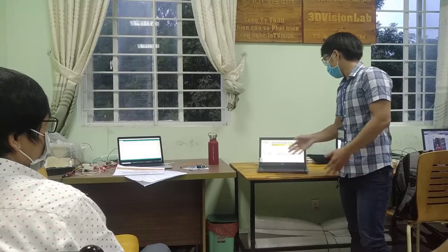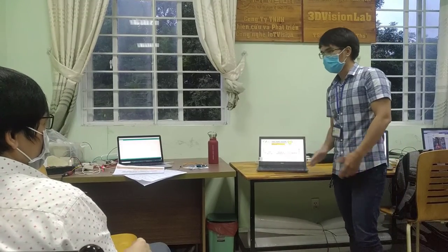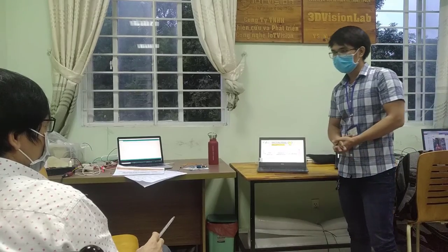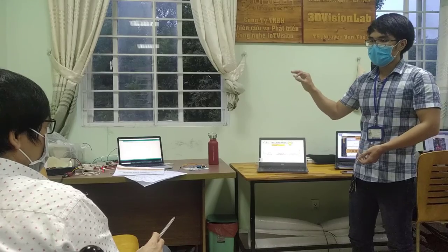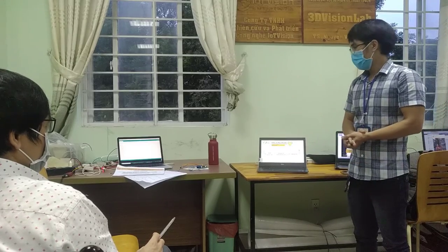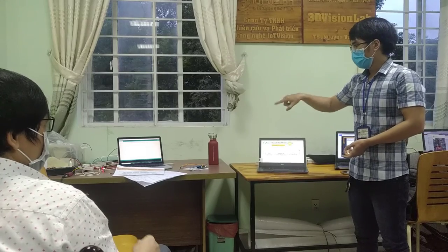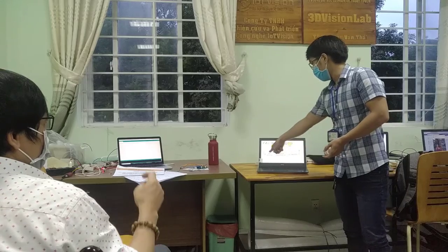And the Hough circle transform is very important to detect the circle in the final step of the image processing. In the input, I will add an edge detector. The image area is very big, and I will transform it to a small image with the circle.